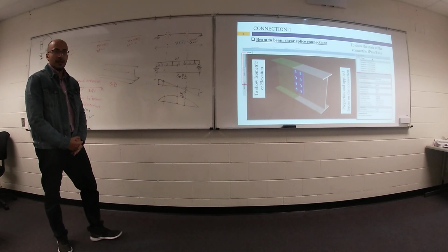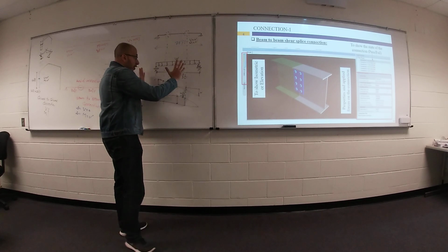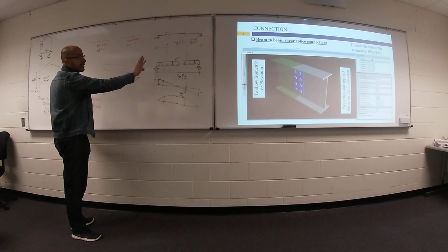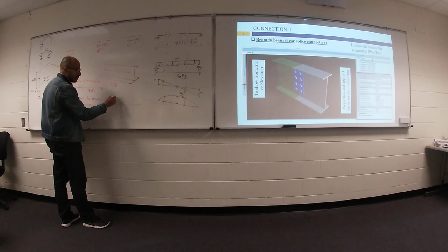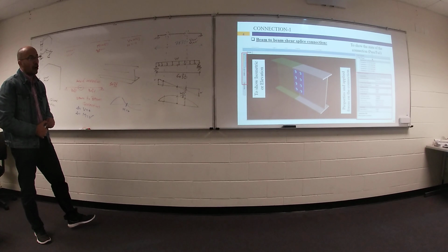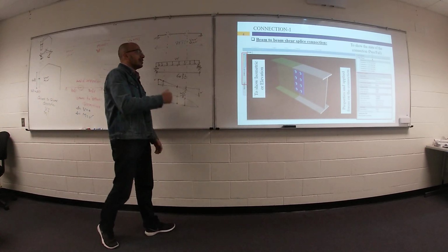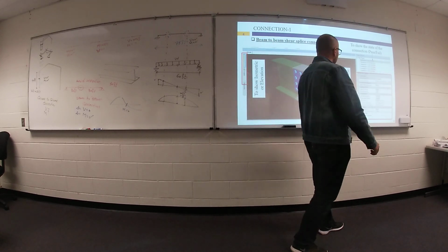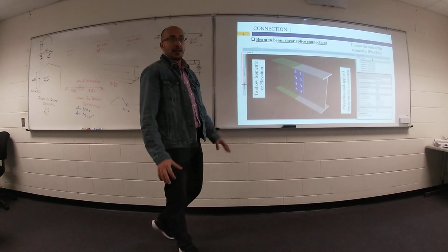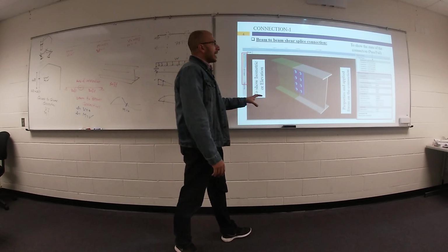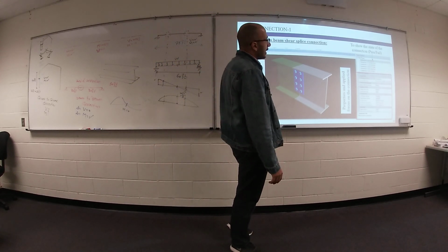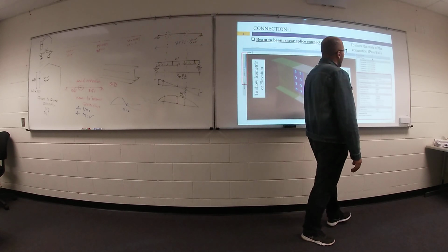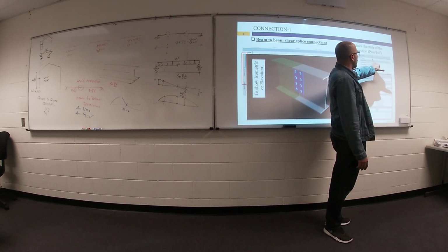You got it? So that means moment equals 0? Yes. Maybe for any reason, because I'm doing a very simple beam, but sometimes your beam has a moment something like this. So at this point we have moment equals 0. Based on your internal forces, I will decide whether this connection will support shear or moment or both of them. Any question? We can build this connection using RISA connection, and the program can tell us if your connection failed or passed, safe or unsafe.